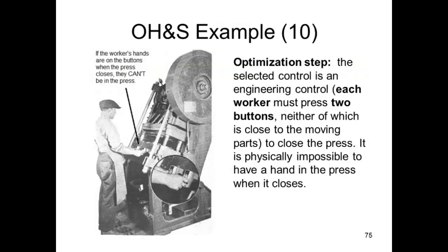So what they did was they had an engineering control. Each worker must press 2 buttons, neither of which is close to the moving parts, to close the press. Now it's physically impossible to have a hand in the press when it closes.